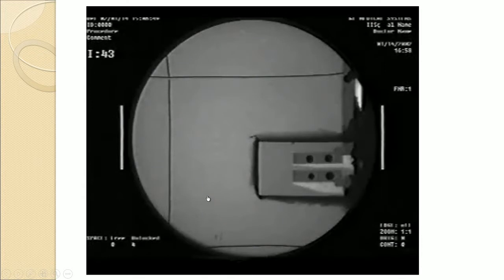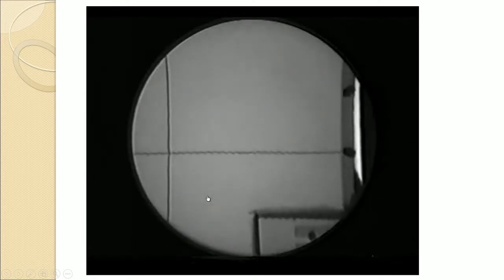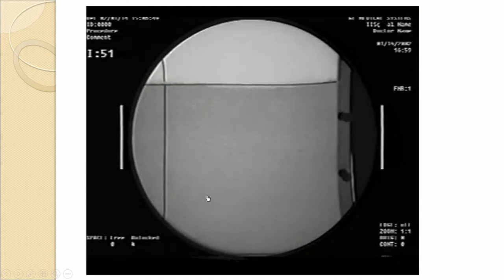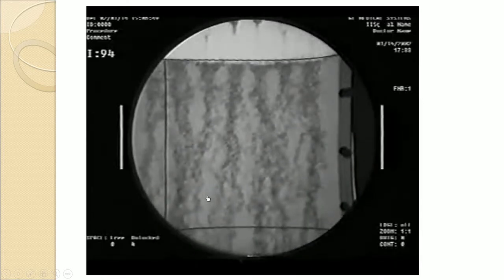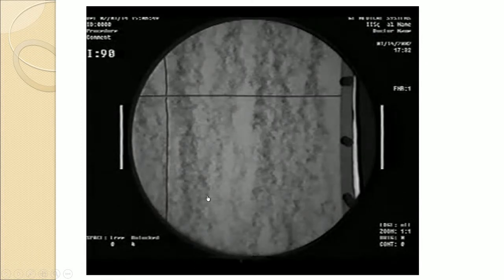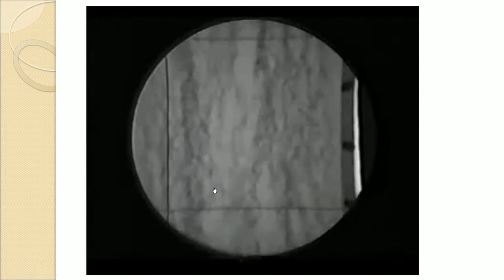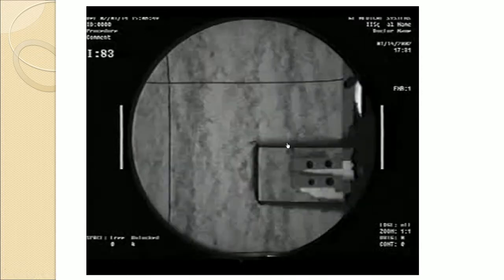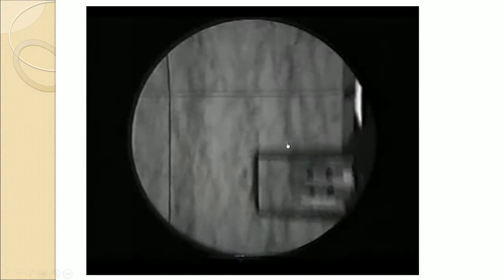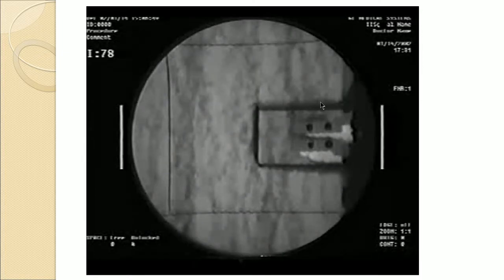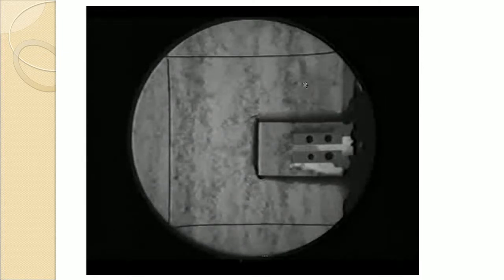So, this video shows that picture which we saw just now, how the liquid flow is occurring in the dropping zone. So, you can see that this is a dry layer bed in the start, and then liquid from the top is poured through the tubes, and you can see the liquid, quite a lot of liquid holdup is there.